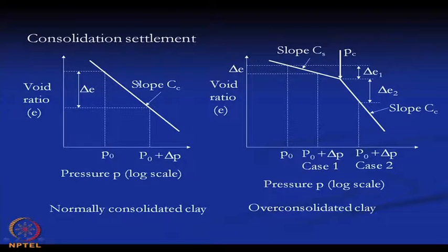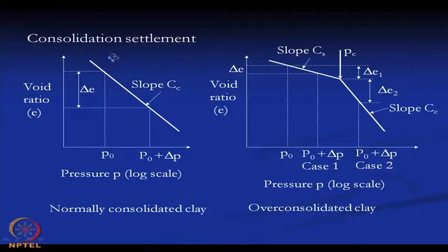Now, how will we calculate the consolidation settlement of a soil? As I mentioned, for foundation design the settlement calculation is a very important issue for clay soil. There are two types of soil we have considered, one is normally consolidated clay, another is over consolidated clay. In the normally consolidated clay, this is the typical loading path that we will consider, the straight portion.